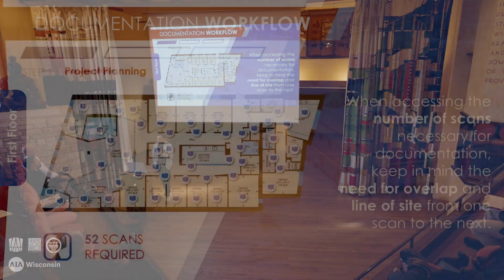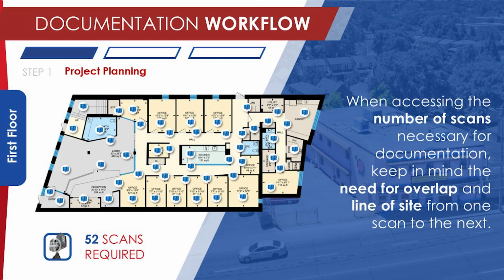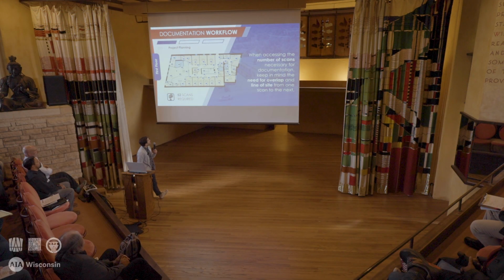So we'll use this building as an example where the first floor is made up of a multi-room scenario, a lot of offices, a lot of blocked line of sight, requiring a lot of scans. So we have this number of 52 scans. Every doorway, you need that overlap, so every doorway, inside every room.